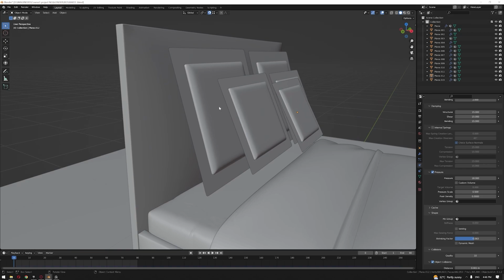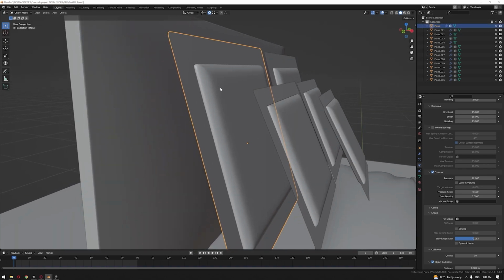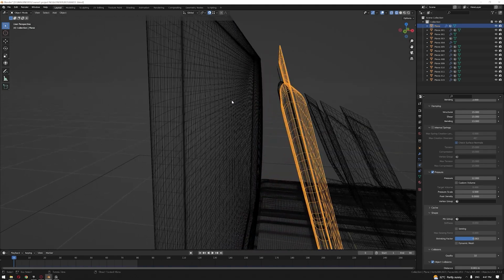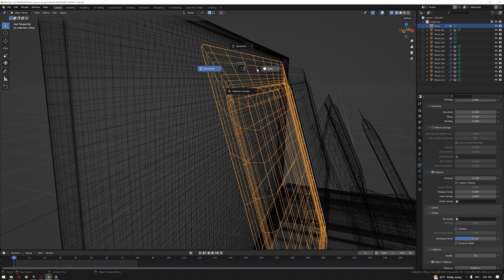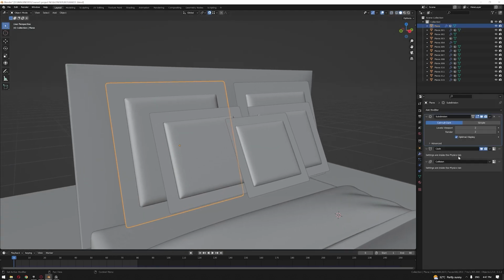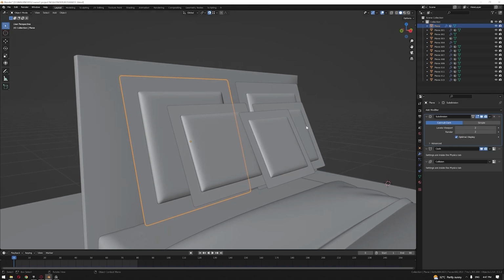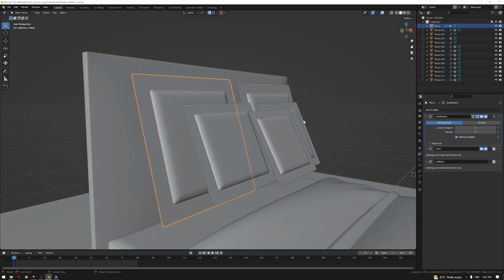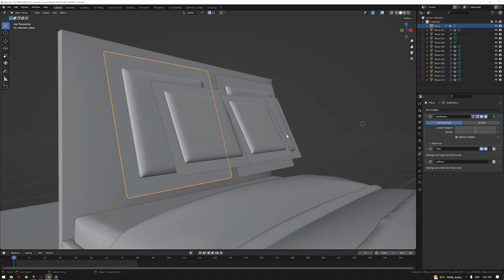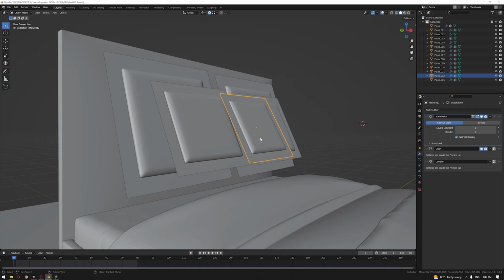For the pillow, we have created a simple box shape and extruded the edge of that box. Just a simple face, no thickness or anything. And then in the modifier panel, we applied collision and subdivision with cloth properties physics on. The main idea here is that we added the subdivision after the cloth. So this is what we were referring to. We want to simulate this object after it have been subdivided.